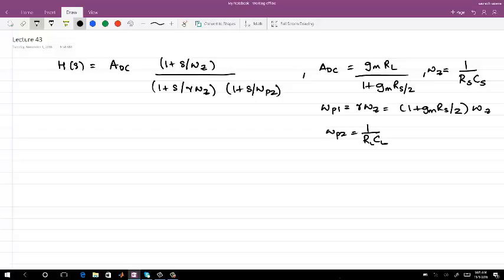So these were the parameters which we had, and we said that we need to decide on these parameters. And the method which I told is that you start with a DC gain, pick up some value, whatever you need to begin with. And the second is you need to know what kind of equalization you need to do, which is the A peak by A DC, which will reflect the channel loss in the system.